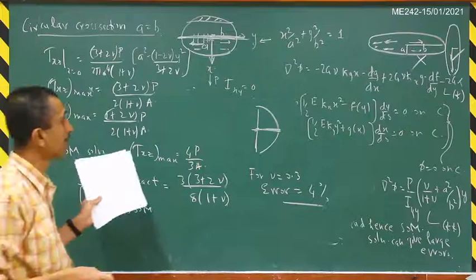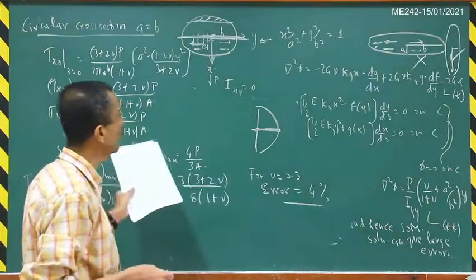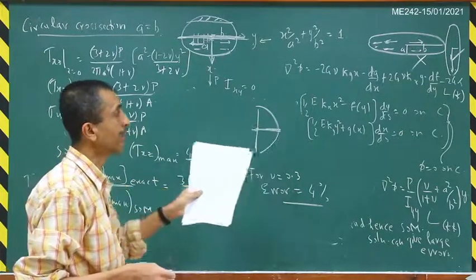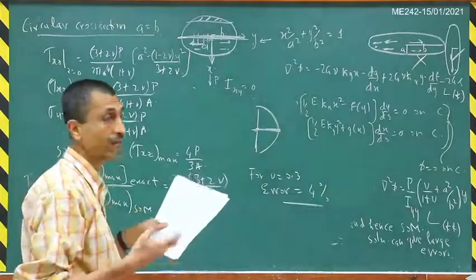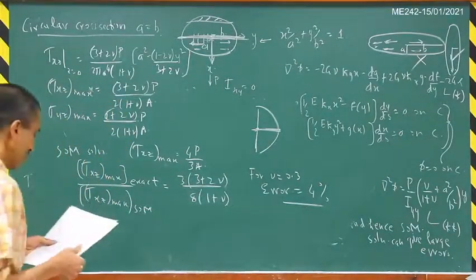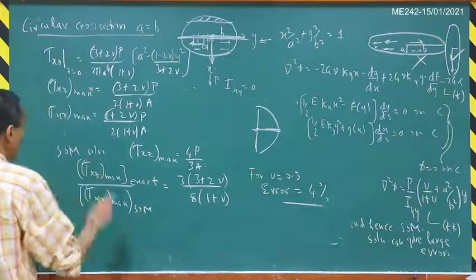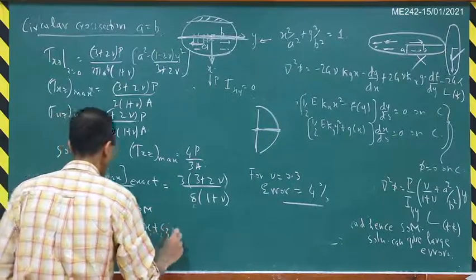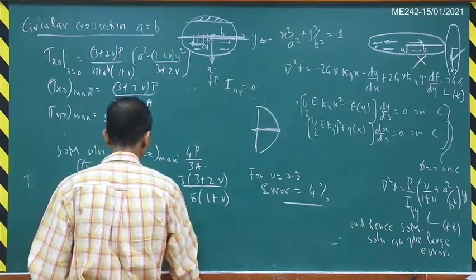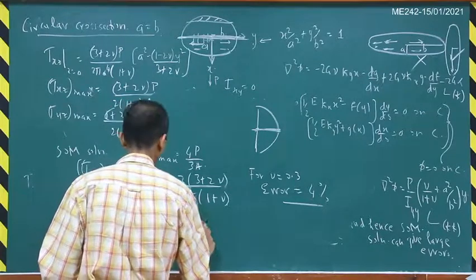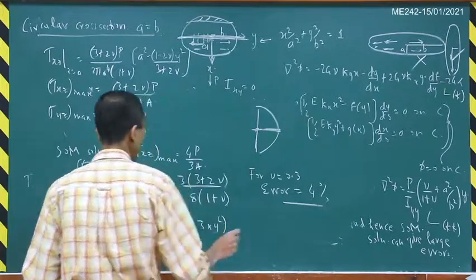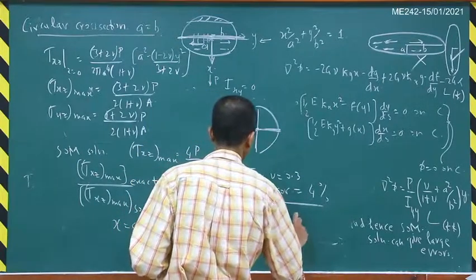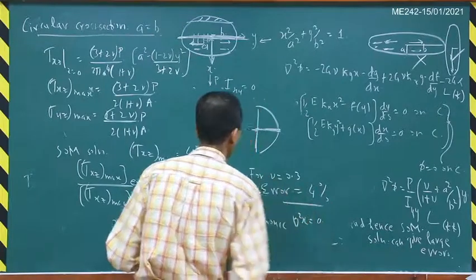Okay, so this example of an ellipse I have solved using the phi approach. That phi is this stress function. But we can also solve it using the chi. In the last class I mentioned that you can use that chi function. So for this elliptical case, your chi will be of the form c1 x plus c2 times x cube minus 3 x y squared. Okay. So you can see that this is a harmonic function. So that means your del square of chi is equal to 0.